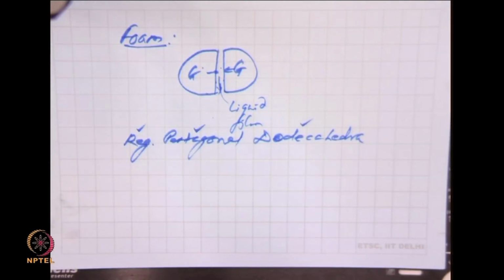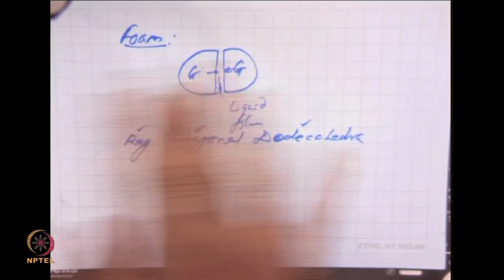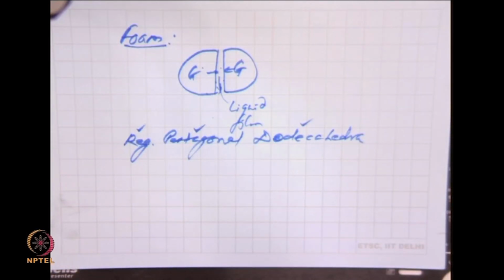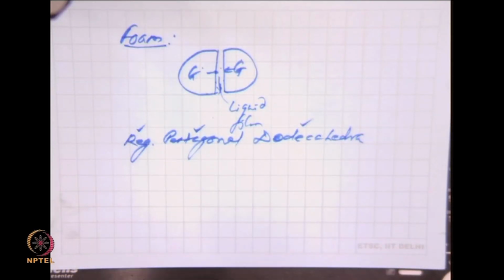So, the common foam that you see with large bubbles, they are polyhedral. If the bubbles are very small, they will be spherical. So, the foam is one which is polyhedral and spherical bubbles are in froth. Some people reserve the word froth if there are particles within the liquid, so that if you let a layer of froth vaporize, it will leave a thin film of solids at the bottom. That probably has to do with froth flotation, which is a much older process compared to other applications of foam.